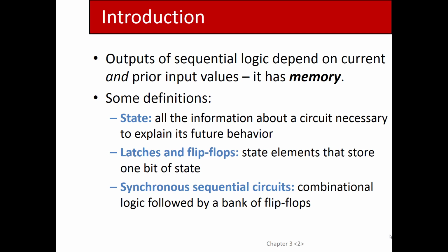Register is a confusing word because it means two completely different things. In assembly language, registers hold intermediate values and are addressable locations in a program. But in a digital logic circuit, a register is just multiple flip-flops. That's not addressable. It's just a value stored in a bank of flip-flops. Sequential logic is regular gates, and you add in these latches, flip-flops, or registers.